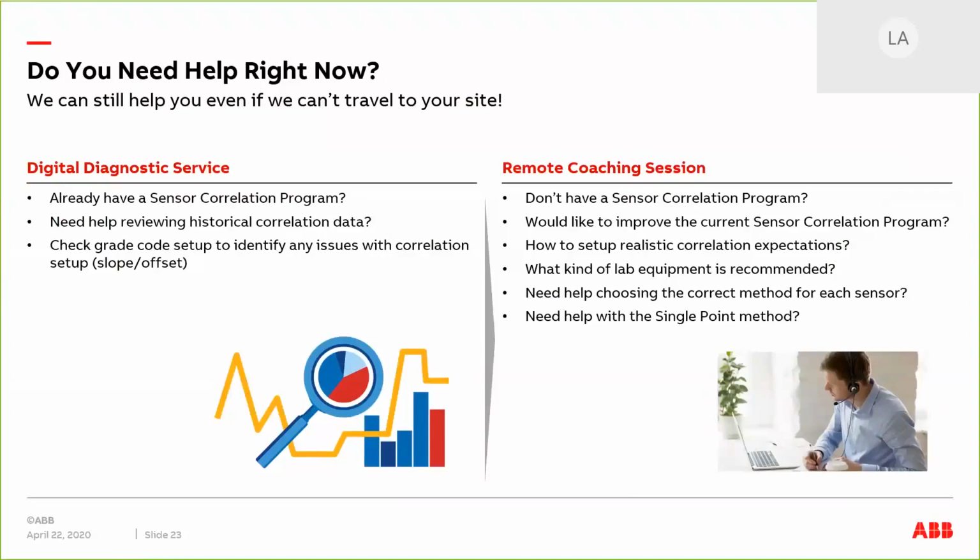Thank you for bringing that up. One other thing, and this goes back to the use of SPC, or statistical process control. I keep seeing people say that if we have so many readings that are high or in a line, at a certain point we'll make a bump to the process. But they don't go back and actually do the actual XY correlation.